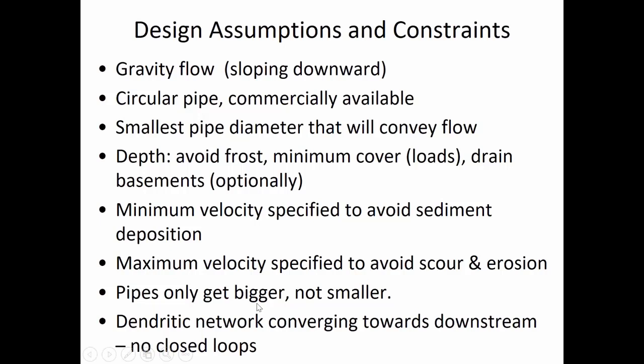And beyond the debris that may be in it, you're just going to be carrying more flow when you have two 18-inch pipes coming together and entering a larger trunk line, so it's going to need to be big enough to convey all of that water.